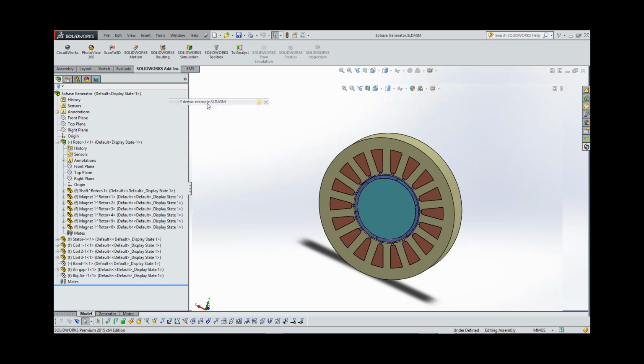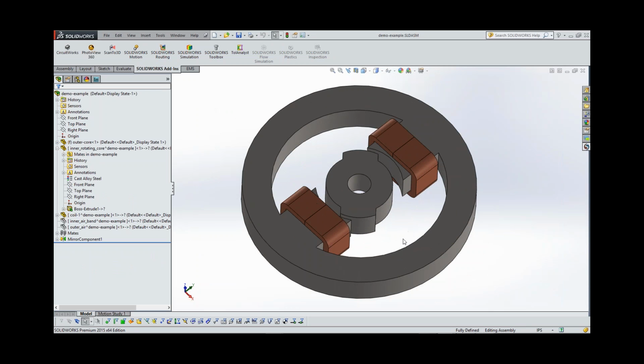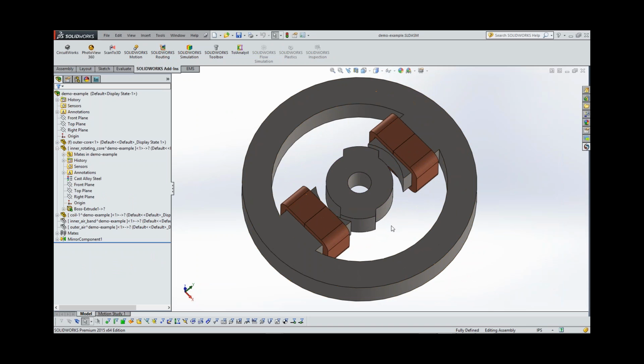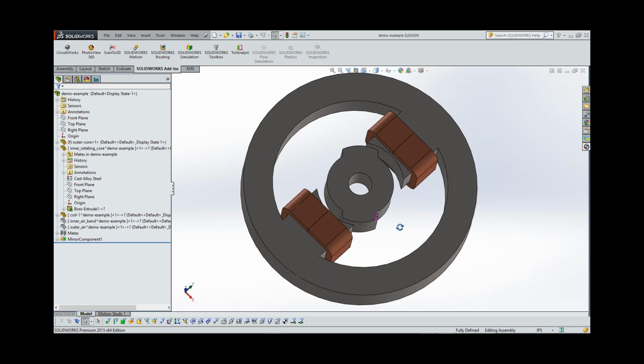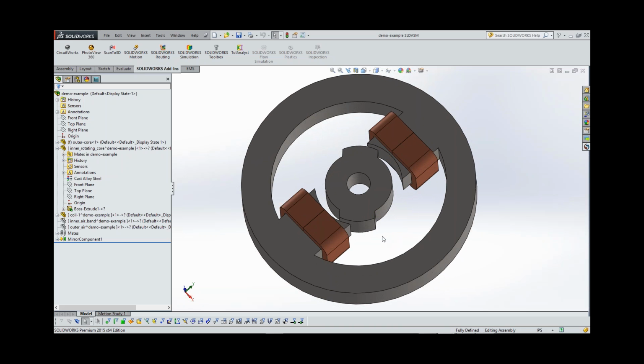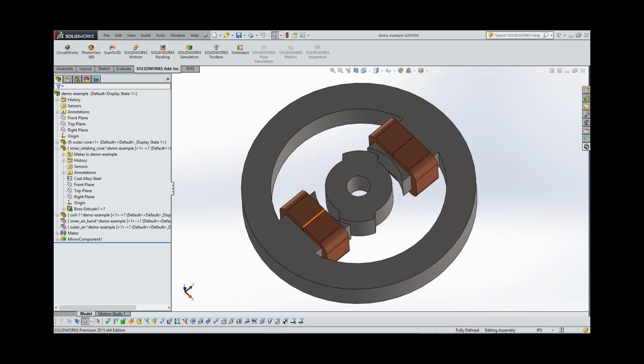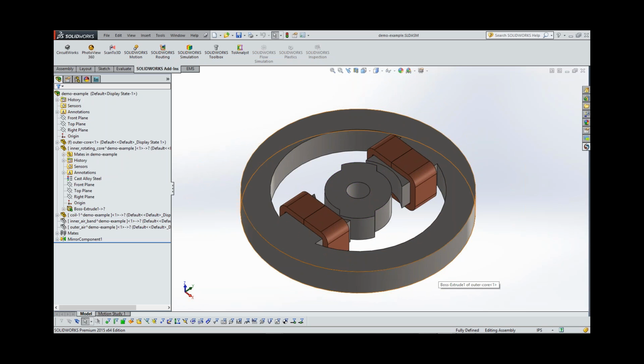So I'm going to start with a simple magnetic circuit here that I have. And this was designed using SolidWorks, and the objective of this particular simulation is, first, to visualize the electromagnetic field present in the geometry, in the ferromagnetic substance, and as well as in the air surrounding them. Number two, we are interested in computing the inductance of my coils here, and finally, what is the torque acting on this movable part or the rotor. Okay? This is a very simple magnetic circuit.